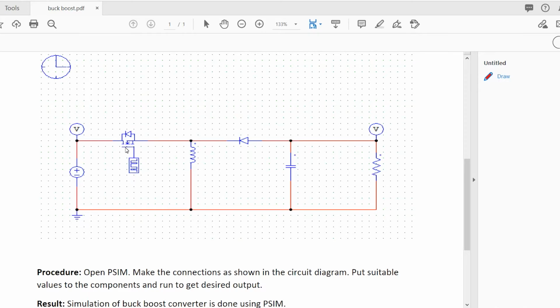When the switch is on, the normal procedure of charging like the previous one will take place, but there will be current flow in the load because the charges were already discharged from the inductor earlier in the second instant, and some charges were stored in the capacitor. Those charges will be released in the third instant. So we will still get the output voltage in the third instant.